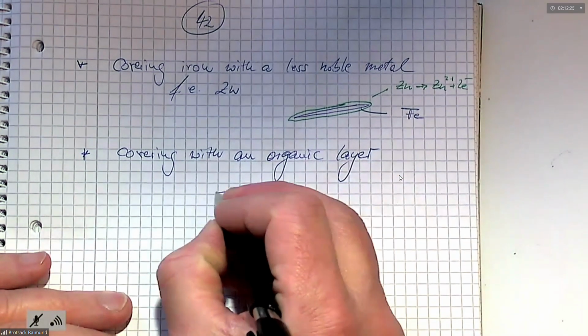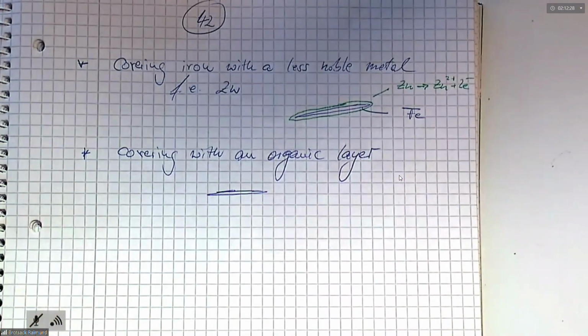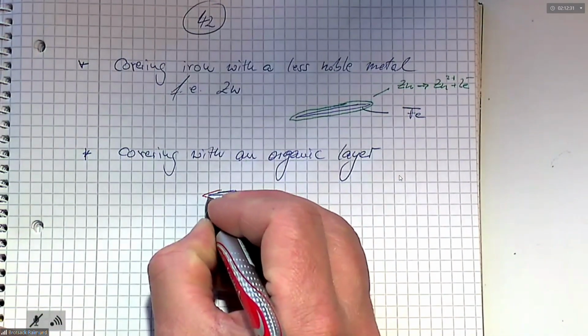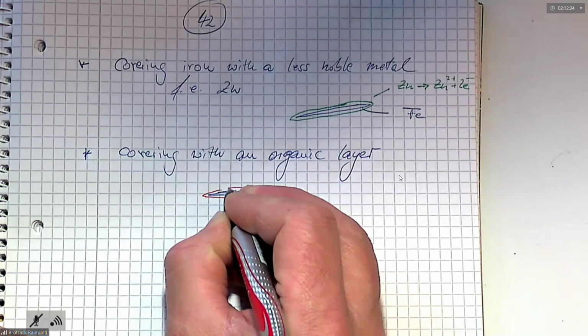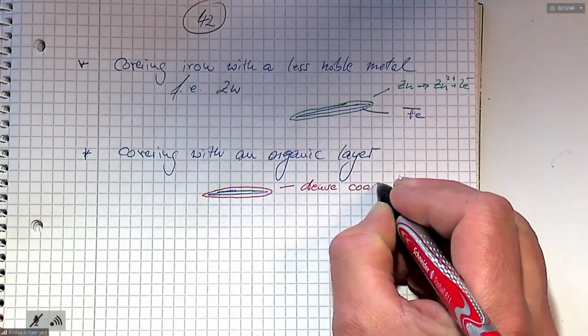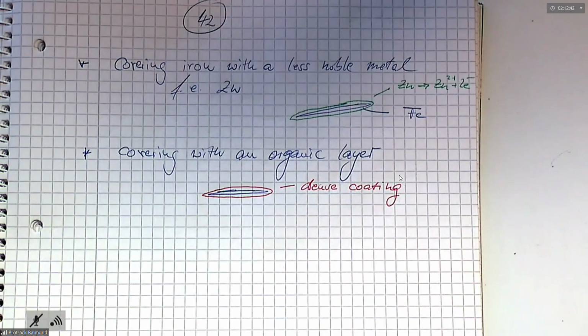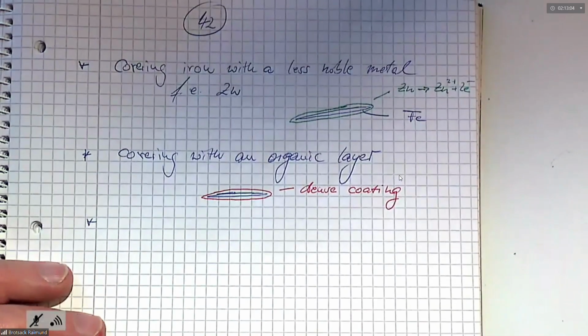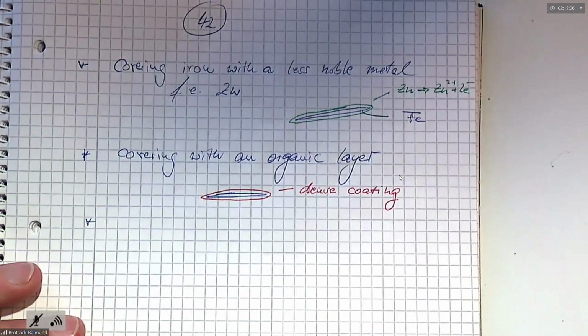So that is similar. Here you have the iron, and you coat it totally. In this case, the function is a dense coating. This is not oxidized and not reduced. It's just making sure that there is no direct contact with the environment. And the organics, of course, don't deliver electrons to the iron, and don't take electrons from the air. What you were talking about with the aluminium, that is an industrial process, and it's called passivation.